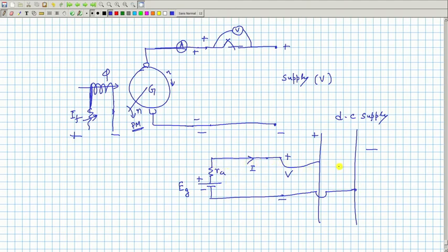That is, it will pump power onto the bus. And on the bus, if it is a DC bus, you do not worry, there must be load already connected, some other fellows are using that DC supply. Therefore, your generator will deliver power to the bus.